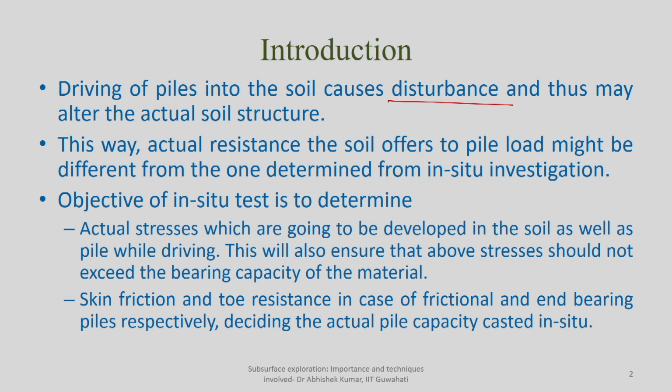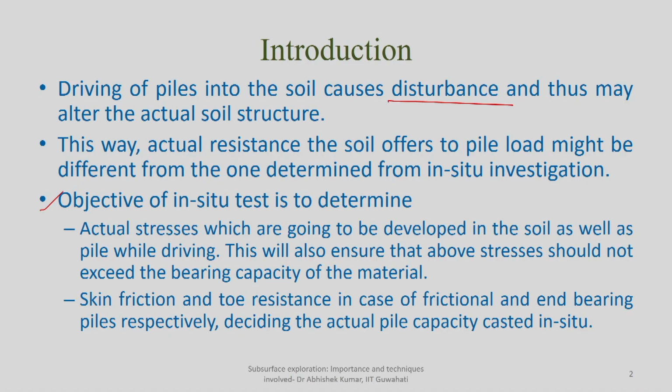So, with this change in the soil resistance to external loading, we have to ensure what the characteristic and the bearing capacity of the actual pile erected at the site of interest is. With this, the dynamic testing of pile, particularly high strain testing, comes with 2 objectives.